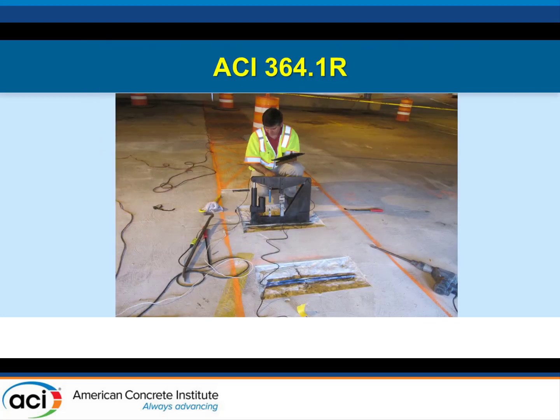Of course, the best way to figure out what's going on with unbonded post-tensioned tendons is to cut them open and do pull tests on them. It's the way that we find is most accurate to assess the tendons, in cases where we know there's degradation, we know there's pitting going on. So we basically do tension tests on the tendons.